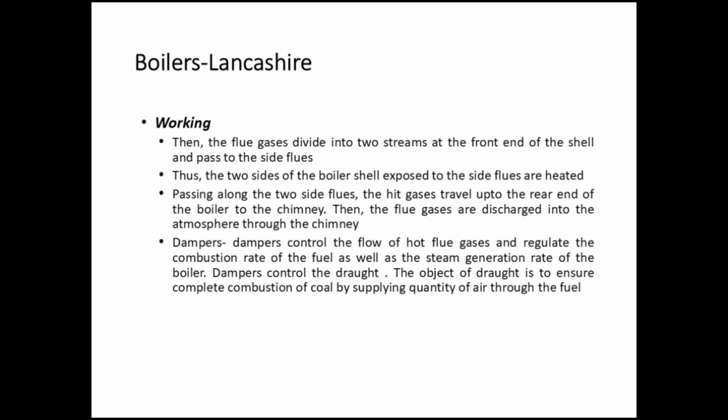Dampers. Dampers control the flow of hot flue gases and regulate the combustion rate of the fuel as well as the steam generation rate of the boiler. Dampers control the draft. The object of draft is to ensure complete combustion of coal by supplying a sufficient quantity of air through the fuel.